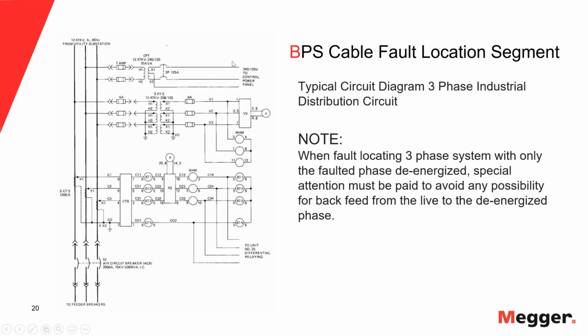And on a side note, some of the old wind farms couldn't be switched around. They had all T-splices in them, and it became a nightmare to fault locate. Today in wind farms, we typically have sectionalizing or switching cabinets also, to make that aspect a whole lot easier, and the most important thing, much faster.